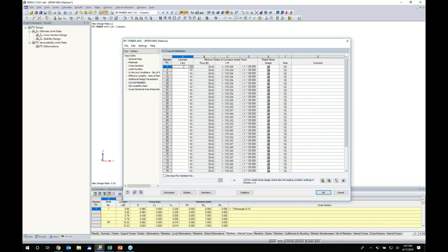And what we have listed here is the thickness of our laminate layers, which is set to 1.5 inches, but you can of course override this. And you'll immediately see a check here of the thickness of that laminate layer over the radius of the member, and we're comparing it to some ratio here. Well, this ratio comes directly from the NDS standard, and I'll show you that in just a minute, but just know we are doing this check before you even run a calculation, and it will flag us if we're exceeding this ratio. We're also telling the program to run a radial stress design. Again, I'll touch on it in just a minute, but by checking this option, the program will go ahead and design that as well.